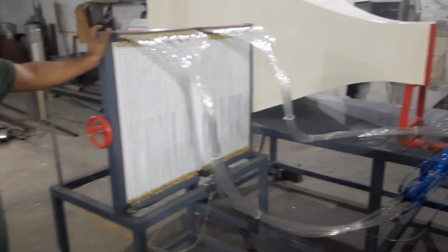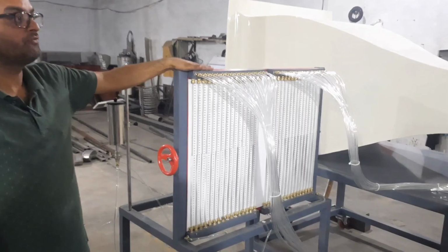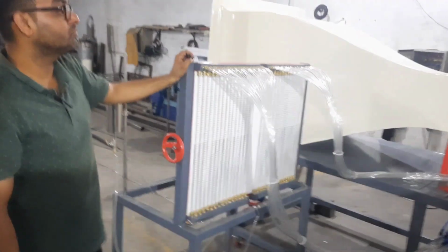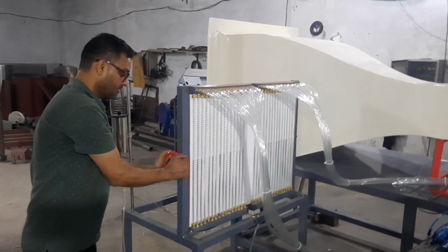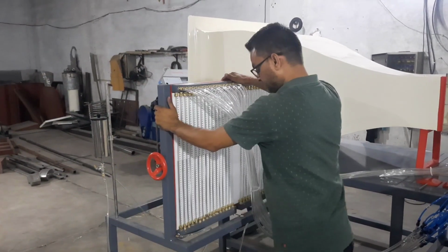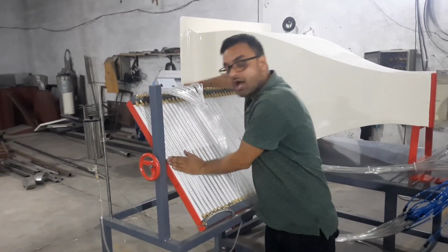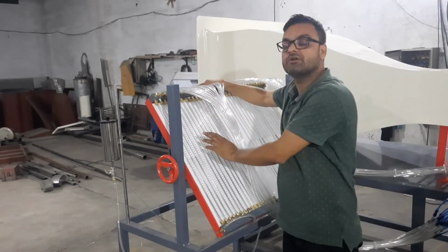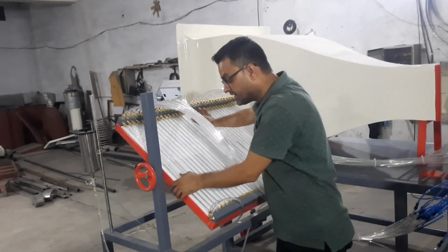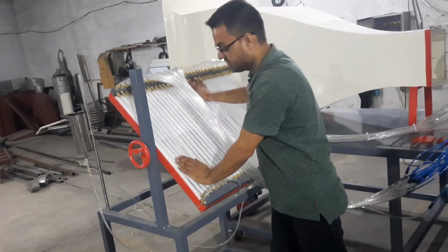Apart from that, it also consists of a manometer, which is a very conventional way, with the help of a pitot tube and an analog instrument, to find the velocity and also the pressure distribution around the body. This manometer can be tilted to different angles. It helps to scale up the readings in case the flow velocity is very low, or the difference between the two points is very small. In that case, you tilt this manometer to scale up your readings. You can tilt this scale up to 60 degrees.